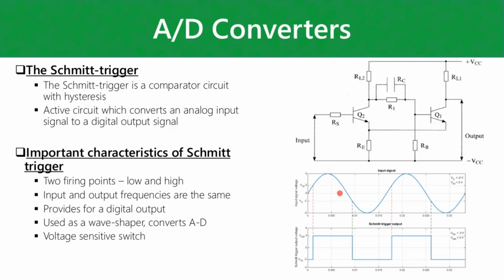So, for instance, I believe one trigger point sits here and the other sits there. In this case, this circuit is now set up so that the moment we get above the upper trigger, you're going to have conduction on your output, so your output is going to go high.